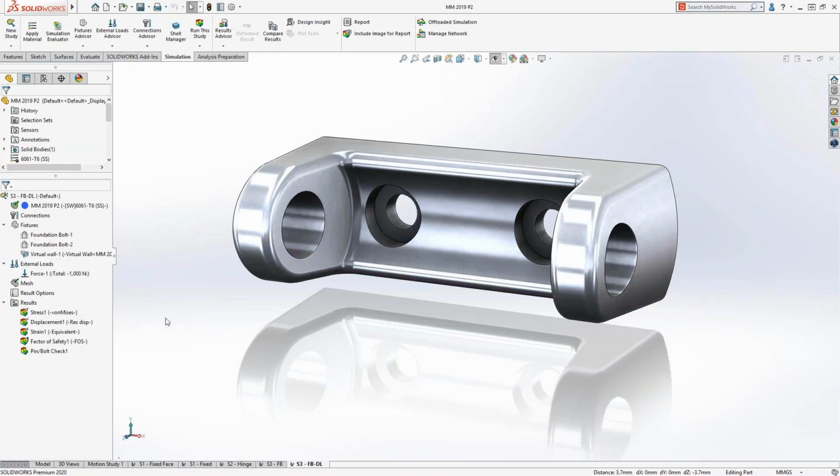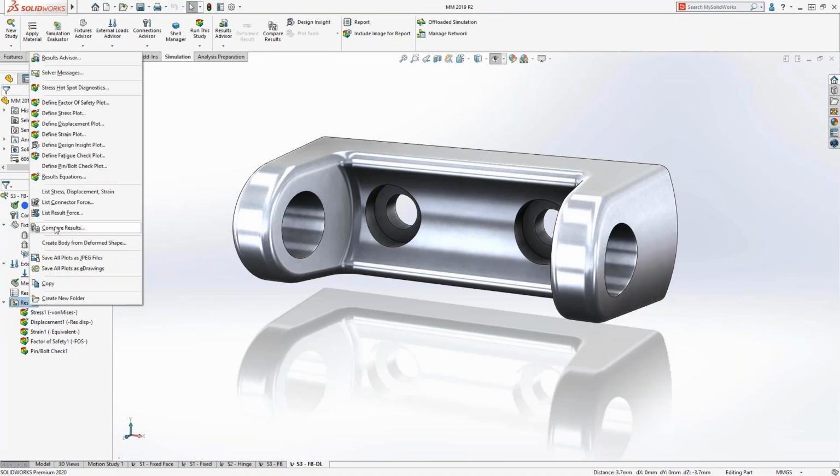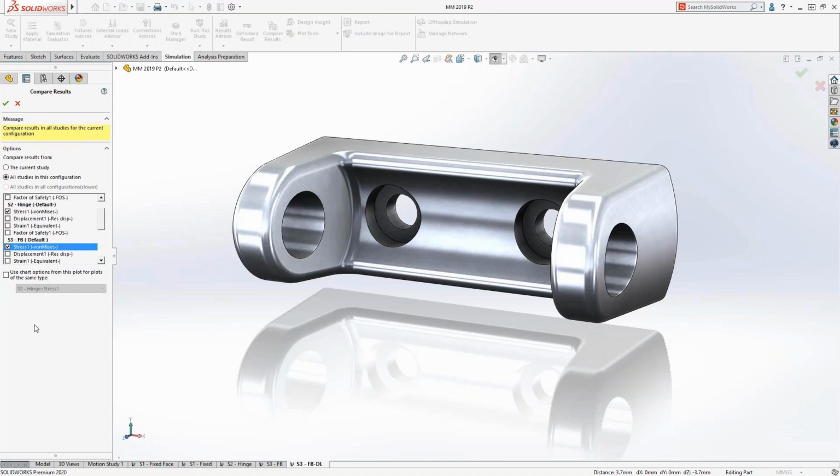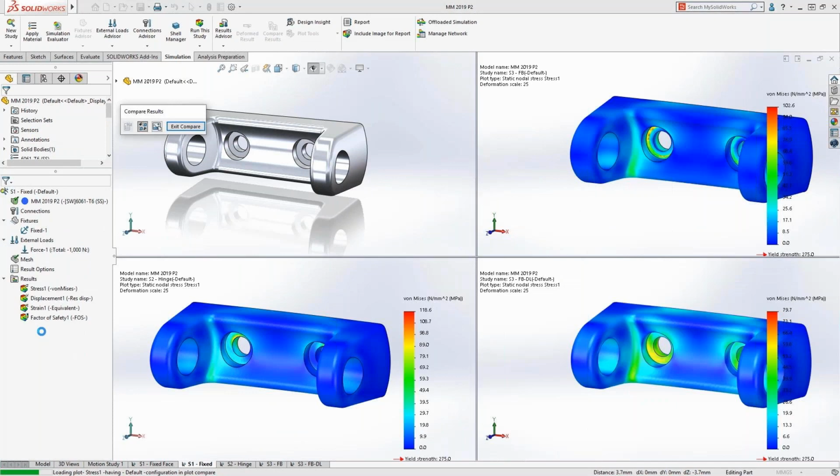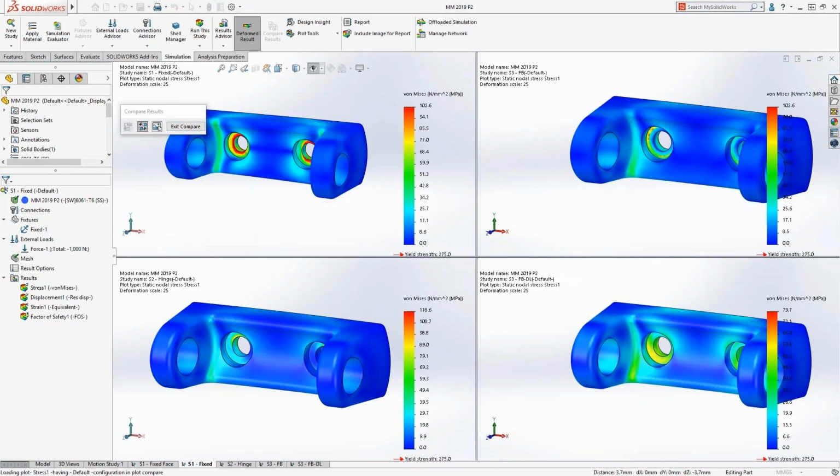So now let's just go ahead and quickly compare those results for stress here. When we look at this, we're going to see that we actually have about 20% less stress when we use the distributed loading, which is the bottom right-hand side there. We also have fewer artificial stress hotspots, which is again, just because all of those nodes are now able to move independently of each other.